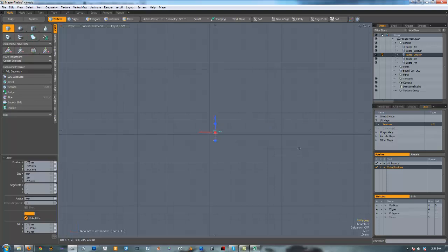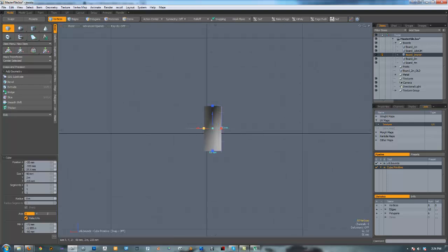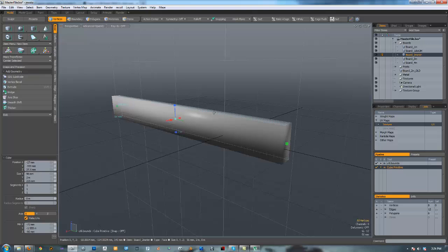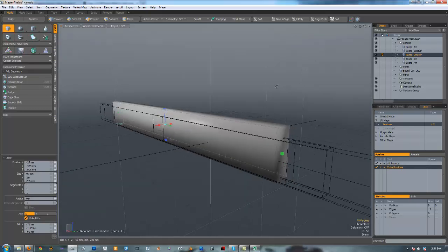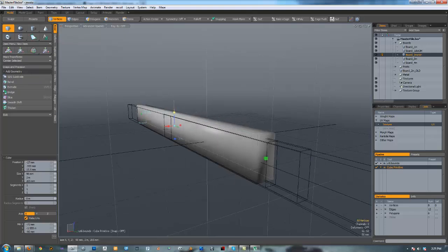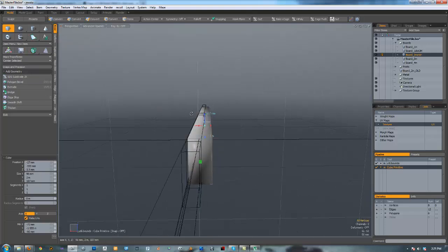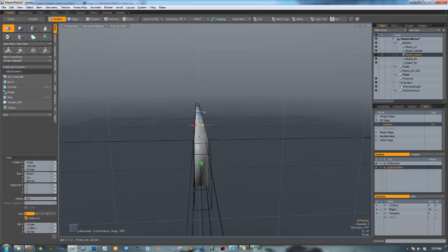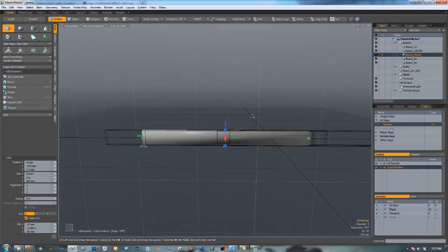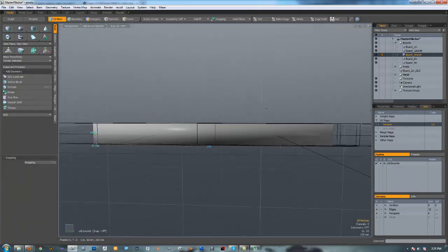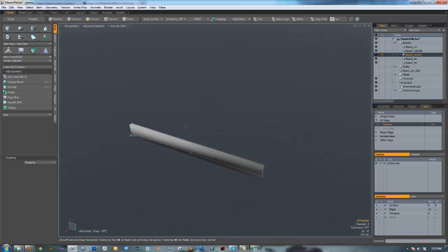Okay, so we'll jump to the front view and bring that to right here. Turn on wireframe by hitting Control 1 and swiping to toggle wireframe. Let's put all of our other meshes into wireframe by hitting Control 6 and wireframe, so we can get an idea of our dimensions here, and we'll just eyeball it. Alright, so there we go. So let's turn off our grid and our work plane and make our meshes invisible.